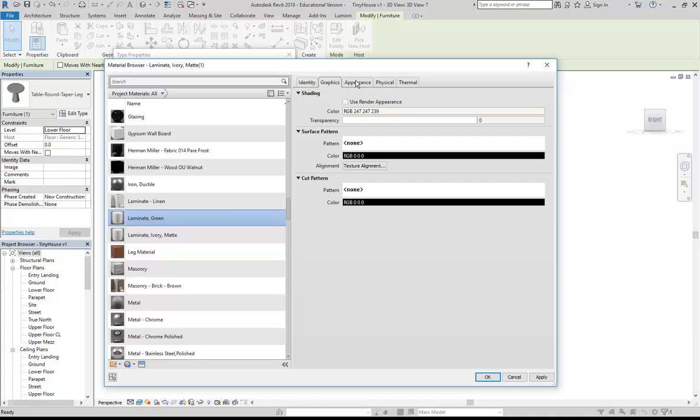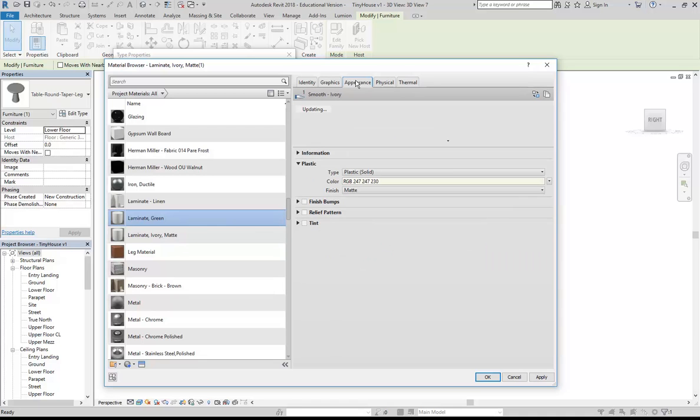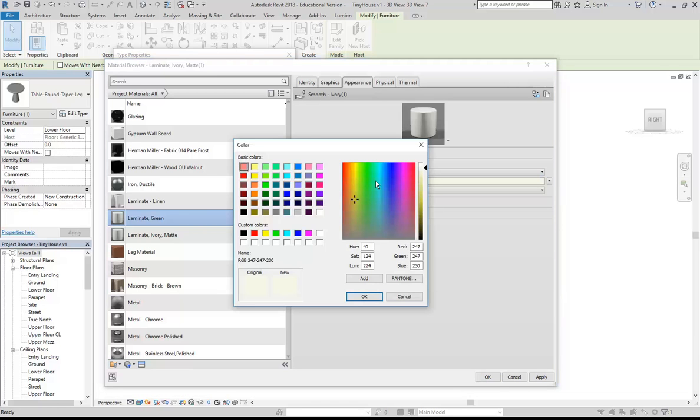And then the appearance. Don't forget there to think about what you're going to do with the appearance. Usually you want to either duplicate or replace. So here I don't need to use replace because I don't need to go to the library. I'm just going to use duplicate. And the important thing there is that you see a 0 above the hand there. So now I'm going to click on the colour and change it just to green, some sort of green. Yep, that should be right.